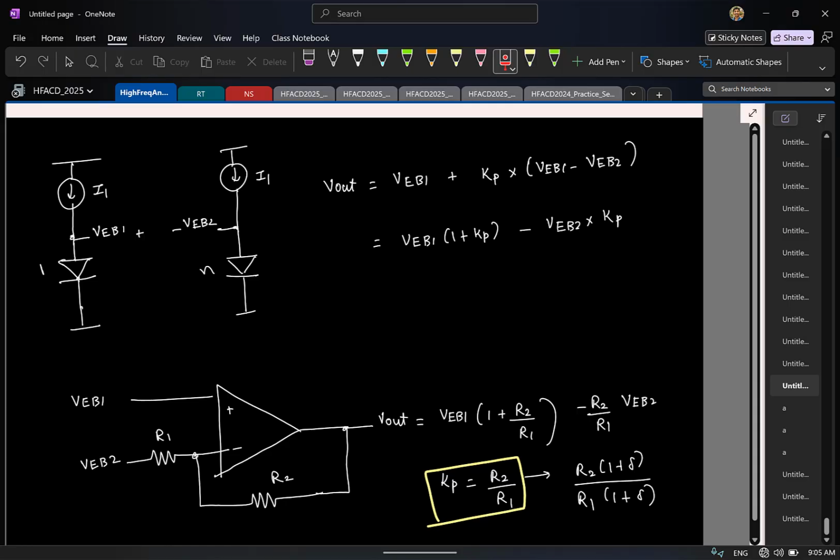So now, of course, here we wanted to have a voltage that is independent of temperature. But what can you say about this gain here? Does it change with temperature or will it not change? It will not change because, independently, the resistor values can change with temperature. But if you realize both resistors using the same kind of material, both their values will change by the same factor. So the ratio kind of cancels.